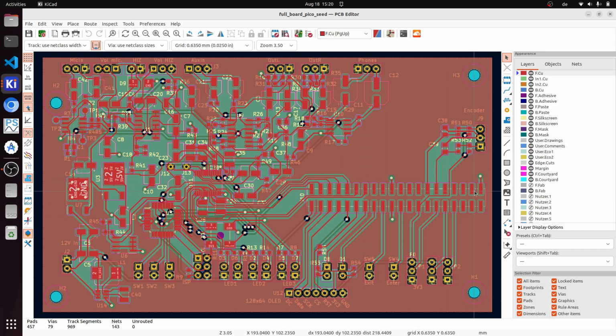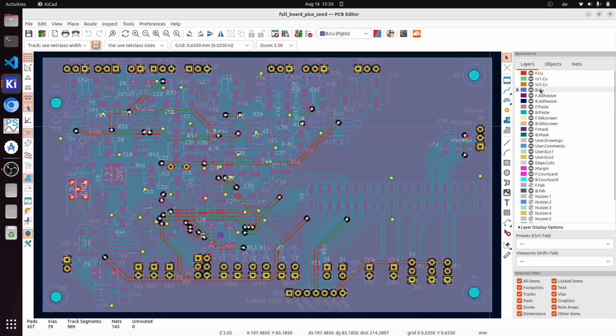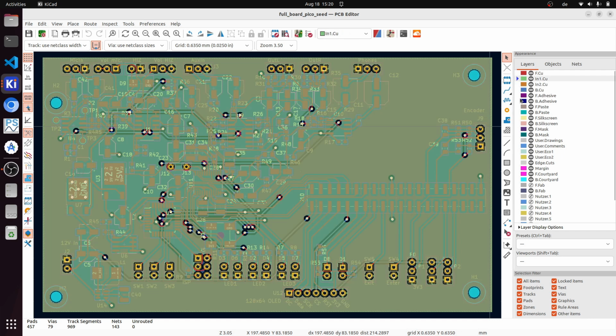And one principle which should be followed is to have a ground plane which doesn't have too many cuts. So I decided to build it using 3 layers. On the front layer is just the main connector. I first of all tried to put as many connections on the front part. Where this is not possible, where traces need to cross, I also switched to the back layer here, which has much fewer connections than the front layer, and one of the inner layers is then the ground plane.